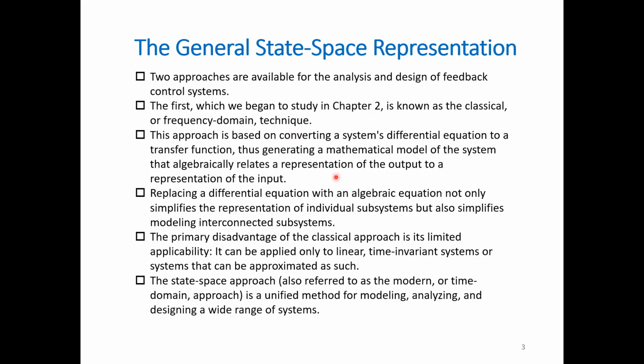You understand? First of all, we converted the differential equation to the transfer function. Replacing a differential equation with an algebraic equation not only simplifies the representation of individual subsystems, but also simplifies modeling interconnected subsystems. The primary disadvantage is that it can be applied only to linear time invariant systems or systems that can be approximated as such.